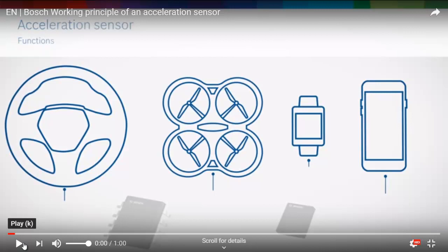That's it. So in this situation, the movement is lateral instead of vertical, as I've shown you before. But in practice, if you want to have a 3D accelerometer, you need to exploit both. You have to exploit the vertical movement in this direction, a lateral movement in this direction, a lateral movement also in the other direction, and also a vertical one. Okay, you're extracting a difference between capacitances for the movements in all three directions. Of course, the real object is more complicated, but I cannot find it.